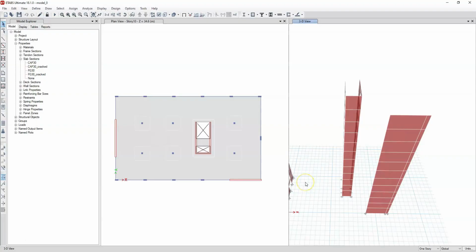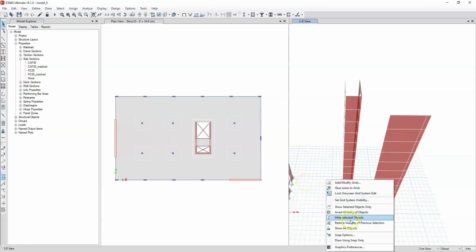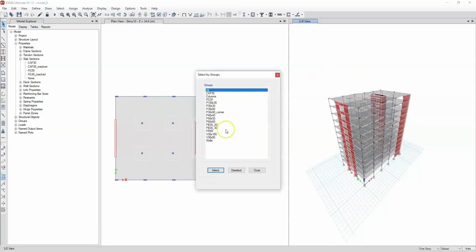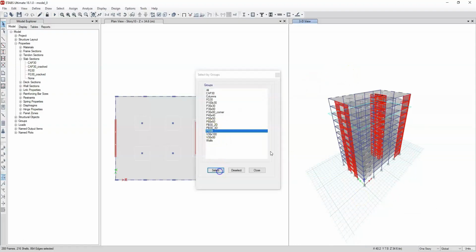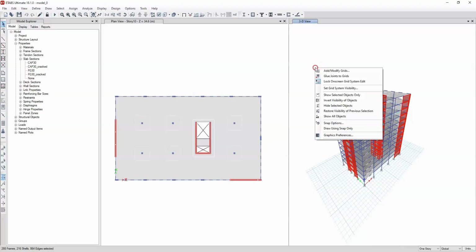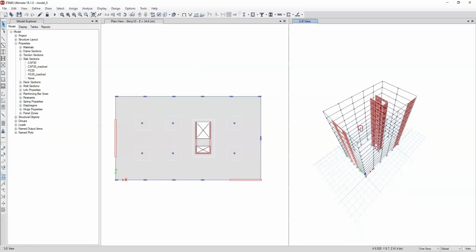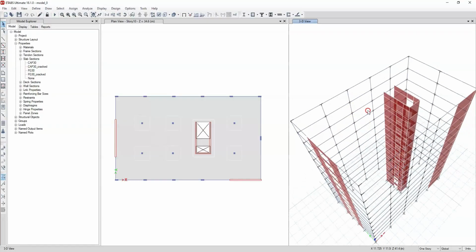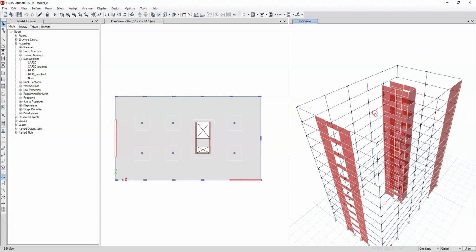Now we will talk about a decision we have already made, which is the distinction between primary and secondary structures. We made a choice. The primary structure considered corresponds to all walls and all perimeter frames of the structure. It is necessary and very important to know that the consideration of being a primary structure depends heavily on the direction.